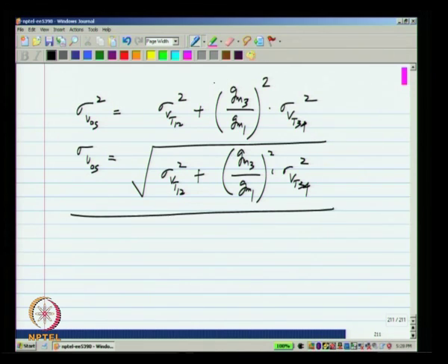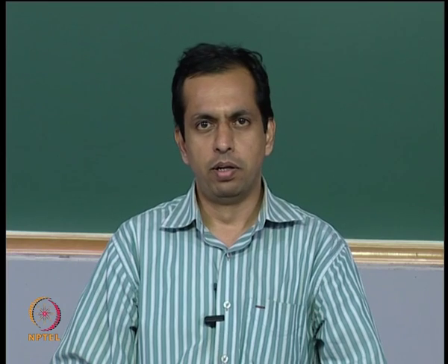Okay. The effect of M1 and M2 you simply cannot avoid, and the effect of M3 and M4, the offset between them, is multiplied by the ratio GM3 by GM1. Now, if you have a small GM3 and a large GM1, it will be divided by a large number and will be negligible. Okay. The way to think about this is that the input transistors M1 and M2 convert the input voltage to a current.